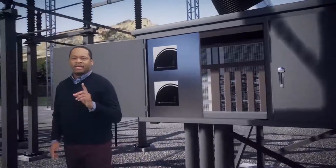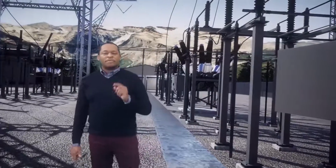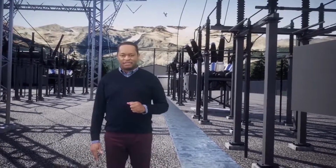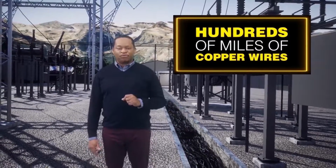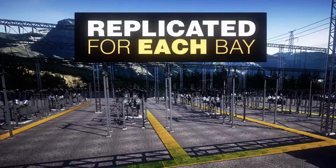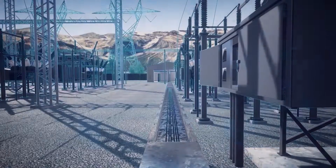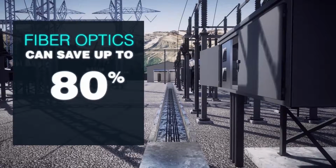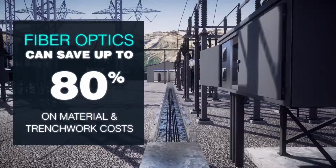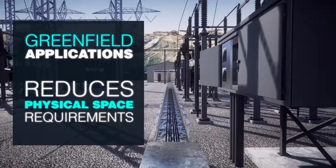Now let's take a look at the conventional wiring and trench works required to transmit analog signals from the circuit breaker to the protection devices. Hundreds of miles of copper wiring needs to be laid through trenches, and this would be replicated for each bay. When copper is replaced with fiber optics, you can save up to 80% on material and trench work cost. And in greenfield applications, the physical switch yard space requirements are significantly less, which is another cost advantage.